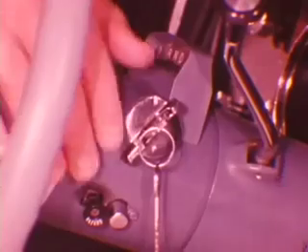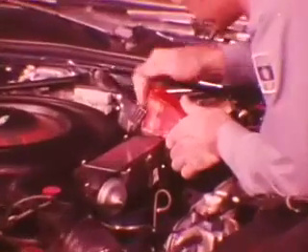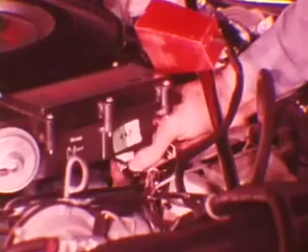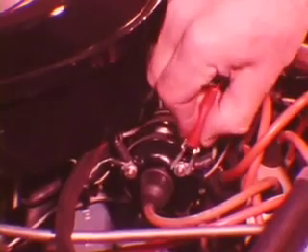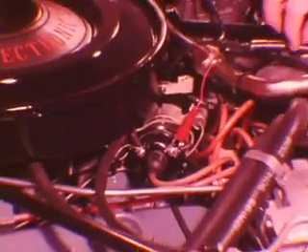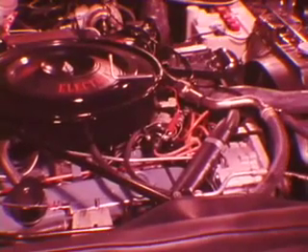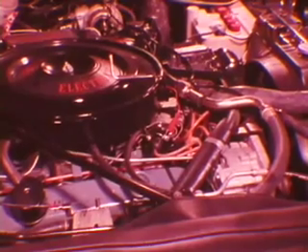Make sure the ignition switch is in the off position. To hook up, remove the two connectors from the computer and insert them into the analyzer connector. Then insert the analyzer connectors into the computer. Connect the analyzer red alligator clip to the coil positive terminal. Do not connect the analyzer coil tower wire to the ignition coil. You will be instructed when to do this later.